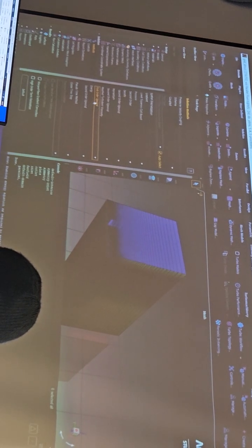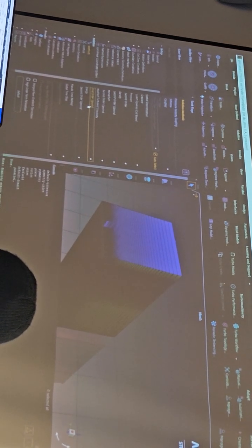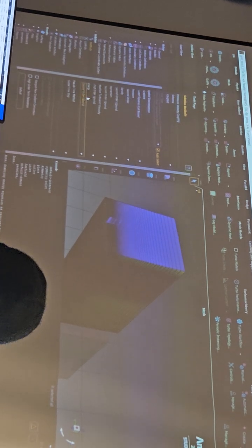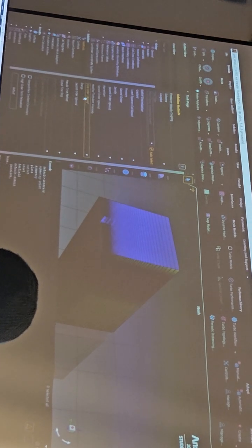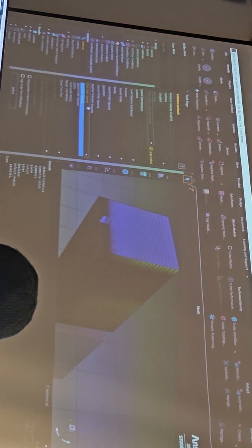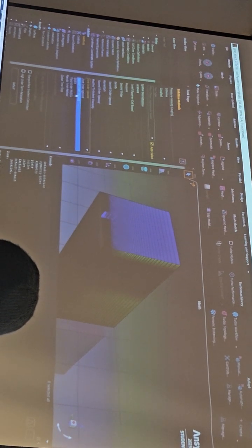The only thing that I changed is the scheme for the turbulent viscosity. So we see that all the other variables are solved with a second order upwind, but the modified turbulent viscosity with a first order.